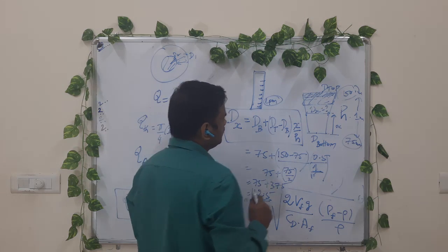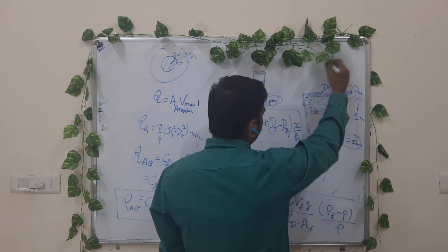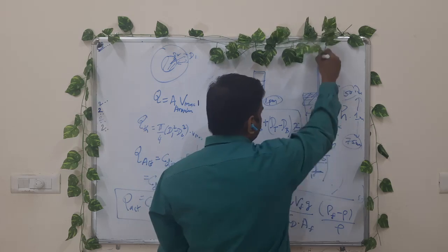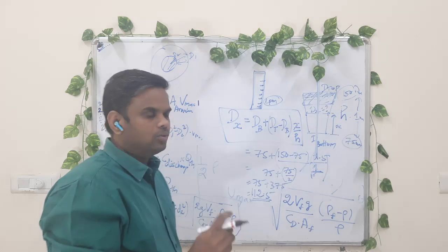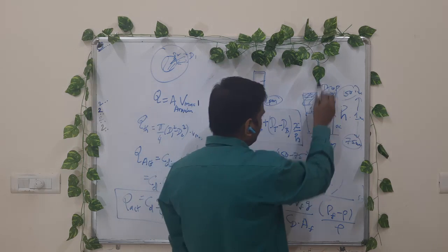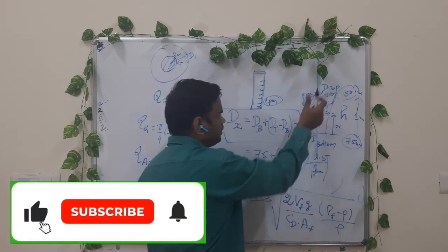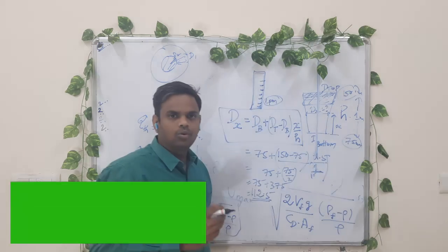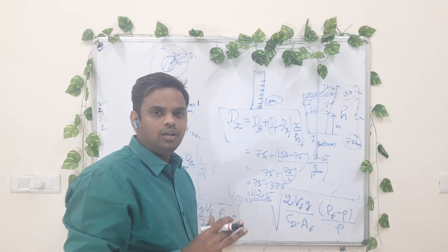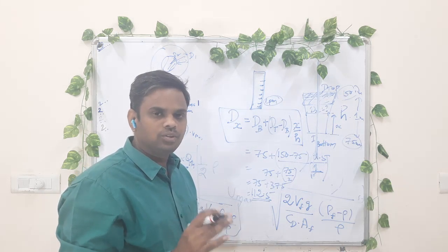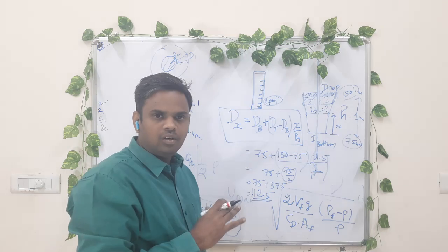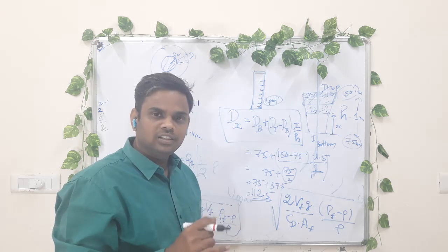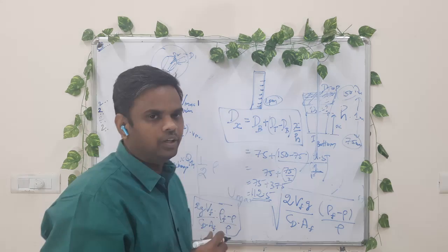Another thing is, to maintain this float in a single position, usually a guiding pipe will be there, over which the float will move only up and down. So that guiding line is also present in the rotameter. That's all about a rotameter. You should be able to list out the working principle, the final expression to determine the actual discharge, and the advantages and limitations of this rotameter.